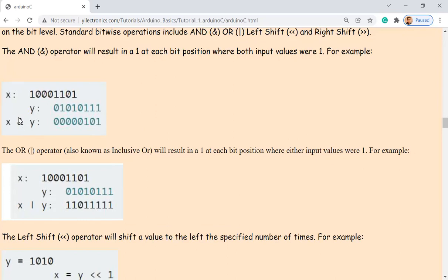It's doing a bitwise operation. So this single operator is doing a bitwise AND operation. For example, Y is a mask now. I have 0 here, 0 here, 0 here, but all the other ones are 1s. So remember in the AND logic, if you AND something with 1, what's going to happen? It won't change that bit, right? But if you have a 0 here to AND with whatever, it's going to reset it to 0.